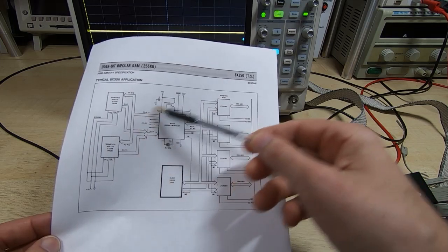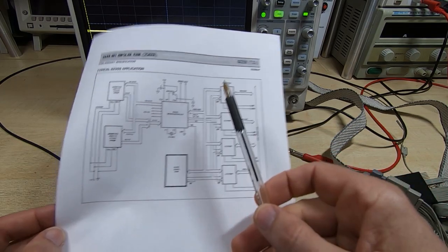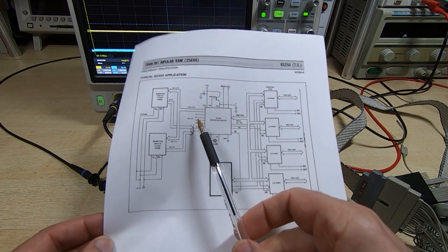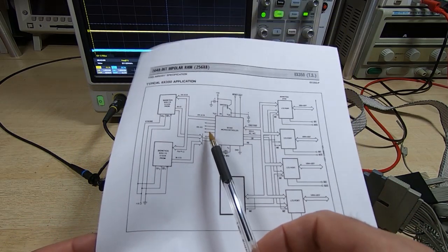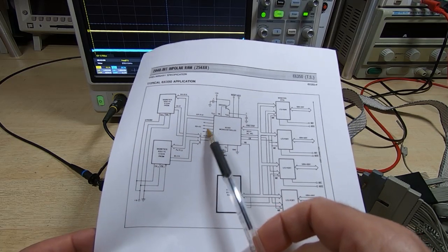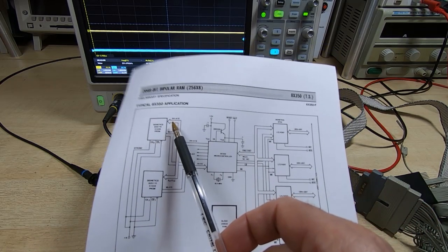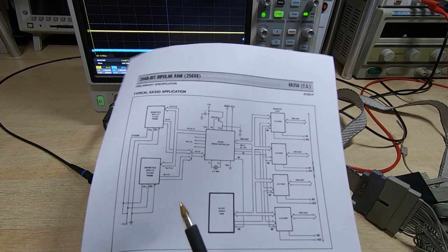Now this processor, again, this is one of the reasons I chose this processor for this particular project, because it is quite interesting. So one of the first things to note, I don't know if you can actually see this, but it's saying address lines here A0 to A3 are not connected in this configuration, but lines A4 to A12 are.